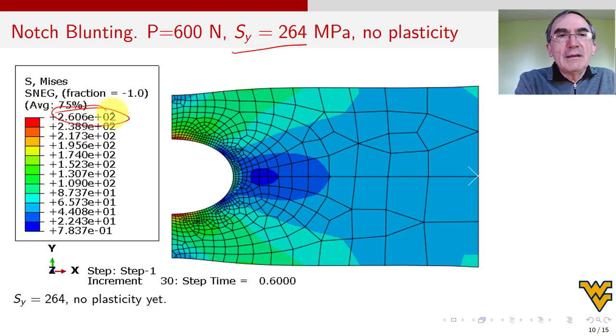So to go to 260, I gotta put this particular load, which is just below Sy. So everything is elastic. And of course, with this load that I put, 600, the stress here is 60, because remember we have to divide by 10. So stress here is 60. Is that right? Yes, because here the blue, you see this blue, between 44 and 65, it's 60.